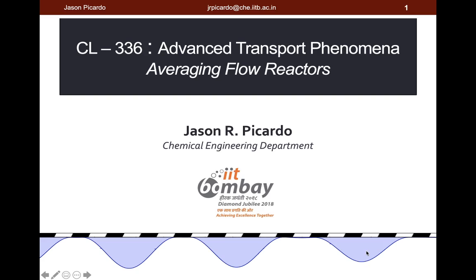And it's also approximately satisfied in strongly turbulent flow in pipes, which has a flat profile, much flatter than laminar flow. But if you do have laminar pressure driven flow, which has a parabolic profile, then the only way you get a plug flow behavior is if you have very rapid radial mixing, which in the case of unidirectional flow must be purely diffusive. So it just means that you have an extremely small Peclet number.